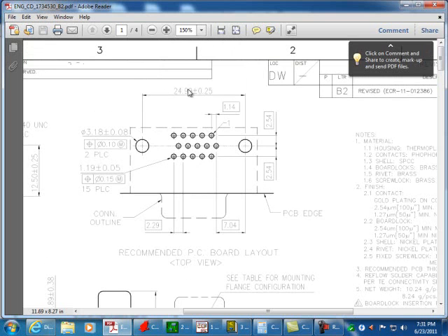One will be outside like this, and then perhaps brackets with another number inside. So it could be inches and then in brackets millimeters, or millimeters then in brackets inches. And in this case there's only millimeters, and sometimes it'll be inches and it won't even tell you. So it's kind of all relative. If it says 25, it's probably millimeters.